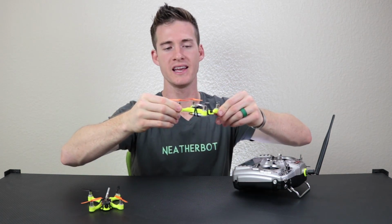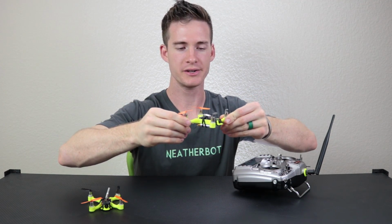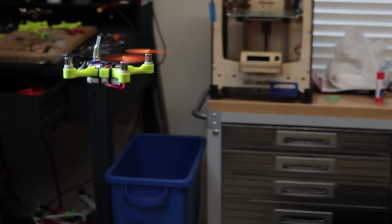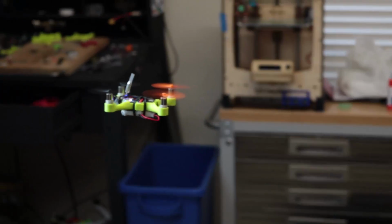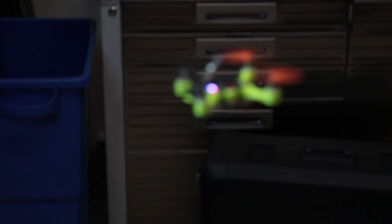As we hover, it's going to be kind of slushy and sloppy, and it's not going to feel very good, and that's fine because none of the other variables have any values. But as P gets higher and higher, you'll start to notice a small oscillation, just even hovering, and then it'll start getting really violent. You can kind of hear it now. All right, I stopped it. I've stopped P from increasing.